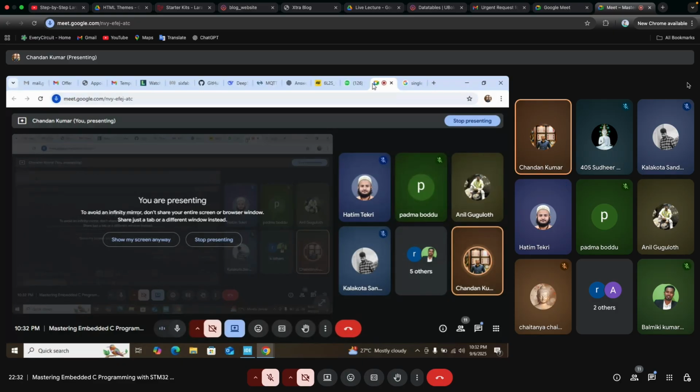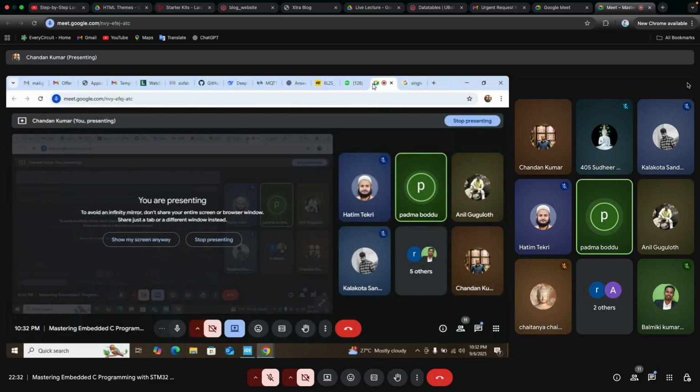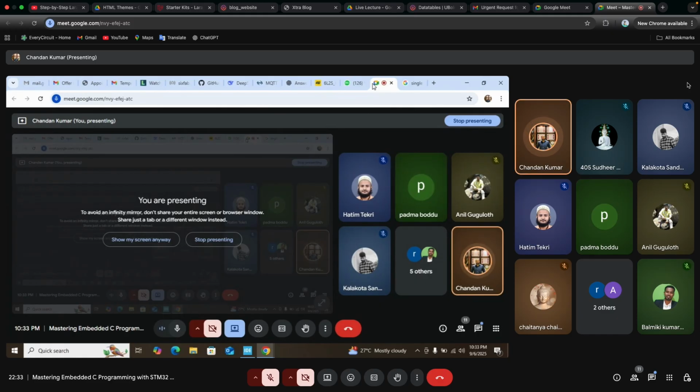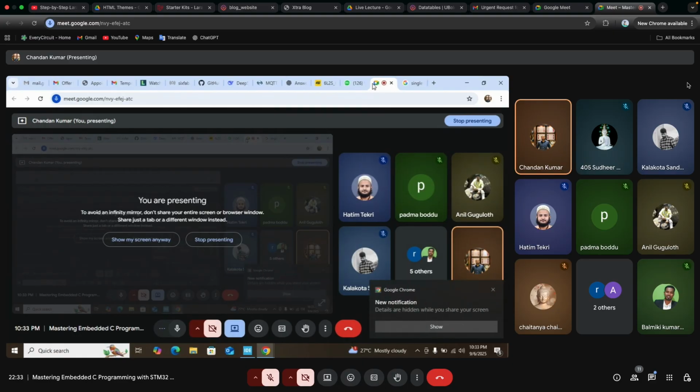Then there will be a read-write bit. For the start condition, SDA will initially be 1 and SCL will be high, also 1. When the transition happens, my SDA pin moves from high to low, and that period is known as the start condition.